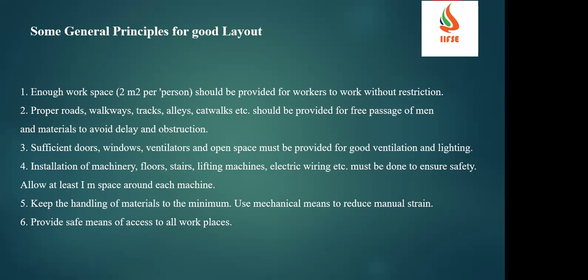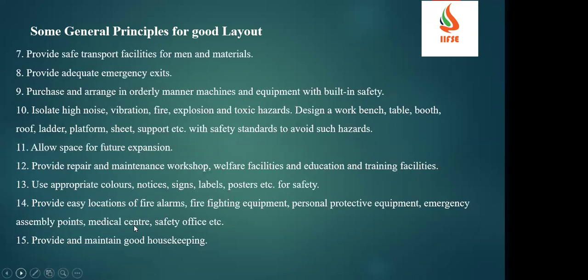Then provide safe means of access to all the workplaces. So how we can reach all the levels. Then provide safe transportation facilities for the men and material, and provide adequate emergency exits for escape, and purchase and arrange machines and equipment in an orderly manner with built-in safety. We always look for the safety controls which the machine comes with. So that is most important.